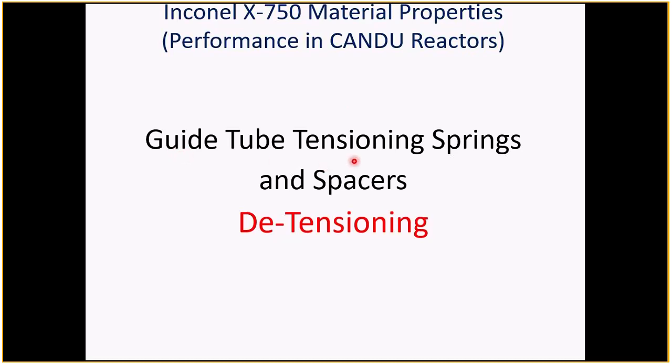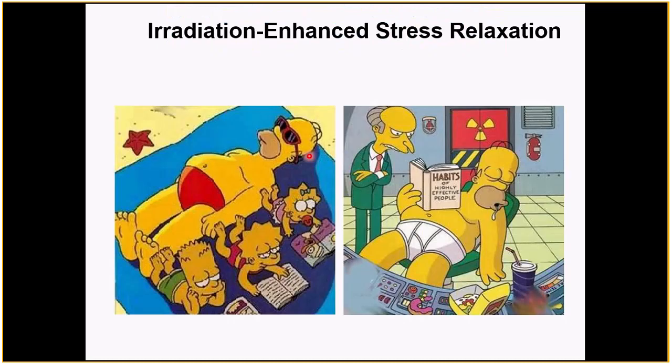So the ability to maintain a load, a tensile force on a component, for tensioning springs, that is important as well. And what happens during irradiation or operation of the reactor is you get detensioning. We get a relaxation of this force. And this is called irradiation enhanced stress relaxation.